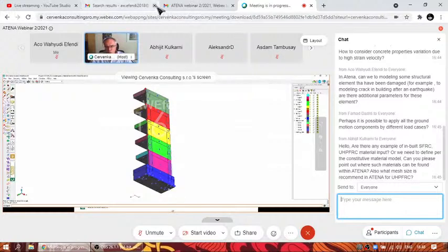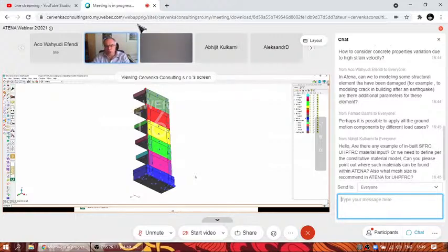Of course, you can also use the first method, as I told you, that you prescribe acceleration at the bottom. But the problem with this approach is that as the acceleration is applied, I'm sorry, the structure will start moving. So it will be moving through your screen. Sometimes this movement may be bigger than the actual relative displacements of your structure. So it is then difficult to see the deformed shape. So a much better way is to use this other method, and that's the method I was showing.